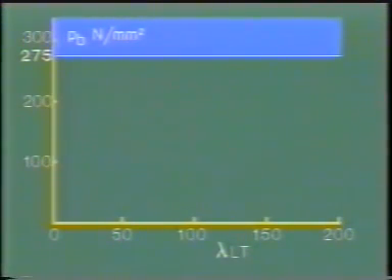Conversely, whatever the material yield strength, the beam can still fail by lateral torsional instability. In terms of extreme fiber stress, this behavior plots as a line which has a very low value when the slenderness is high, but has a very high value when the slenderness is low. This line, too, is an upper bound to the actual bending strength.